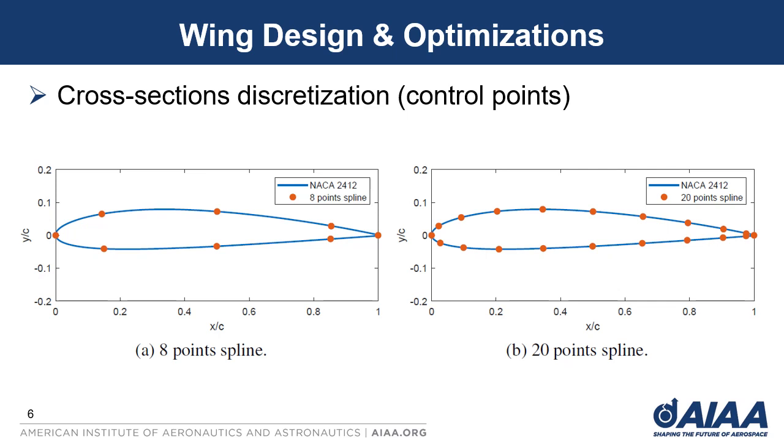So for the wing design optimization, we have here the core of this work, the wing design approach. The idea, once again, is to replace the conventional structures of a wing, such as a spar and ribs, by modular structures, specifically the truss ones. So, since there are no ribs that form the airfoil, some control points are used at each cross-section. These control points are defined by means of a spline in order to guarantee the selected aerodynamic profile.